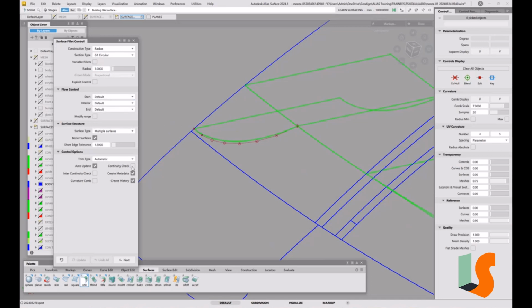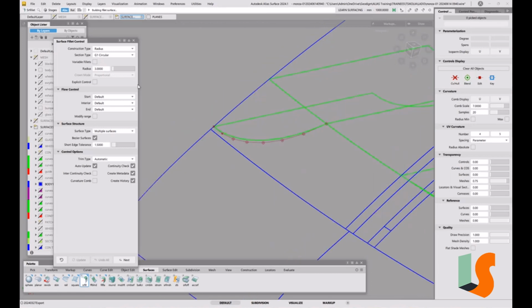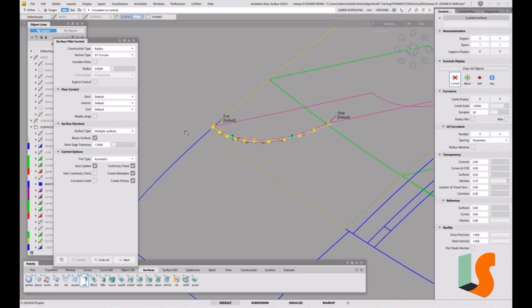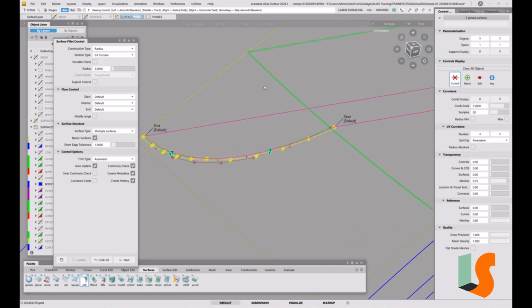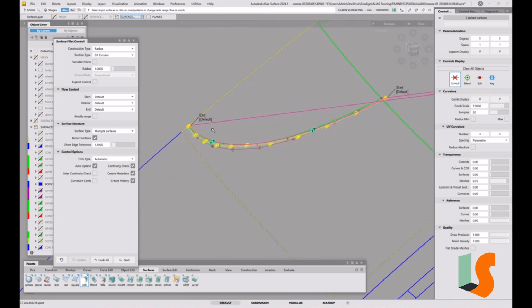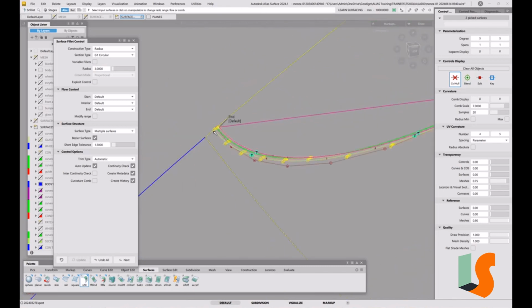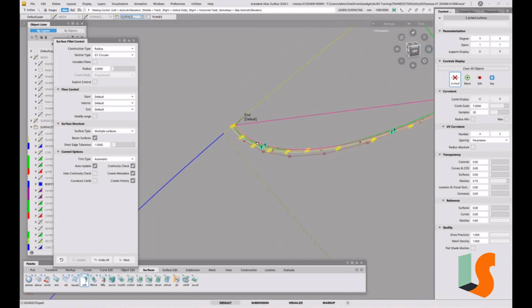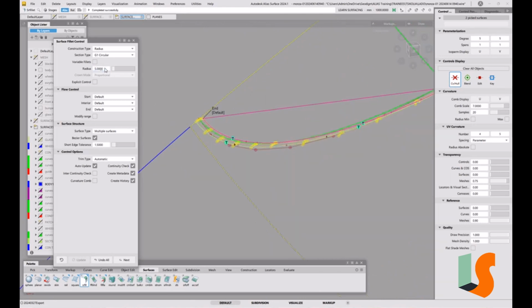I've got history on, continuity check, bearing in mind this is only tangent because it's G1 circular. What you'll find in big car companies, when the fillets get below a certain size, is that in their standards, even for A class, they will say we'll just go with radius fillets, because really at that size you can't see that it's not curvature continuous. I think I'll make that a little bit bigger. Let's make that 5 mil.